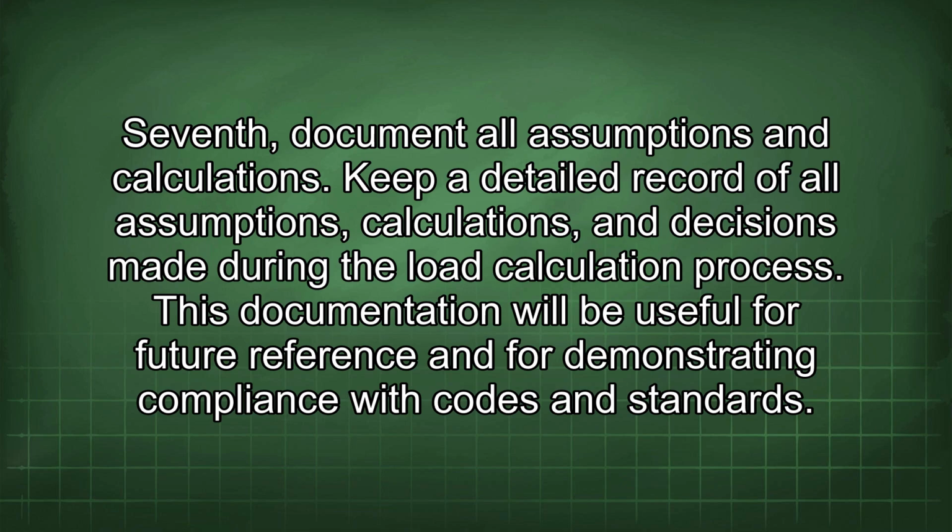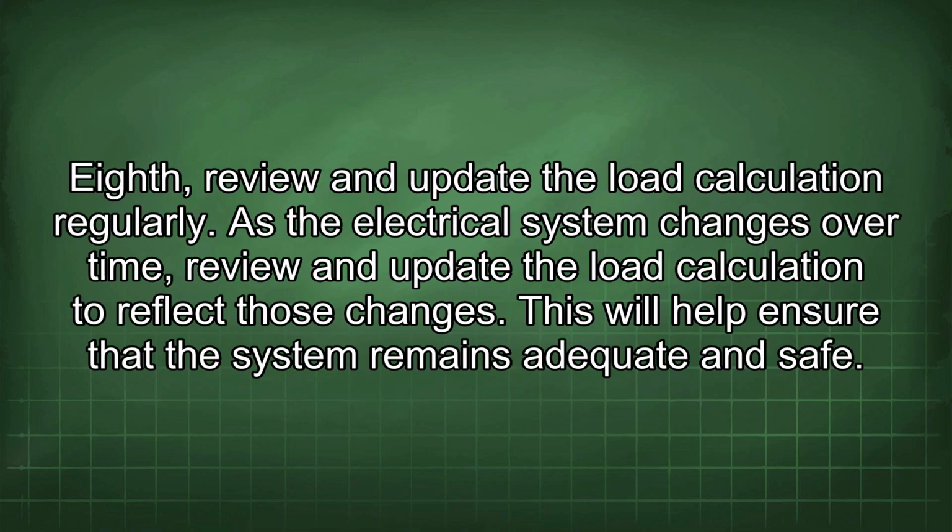Seventh, document all assumptions and calculations. Keep a detailed record of all assumptions, calculations, and decisions made during the load calculation process. This documentation will be useful for future reference and for demonstrating compliance with codes and standards. Eighth, review and update the load calculation regularly. As the electrical system changes over time, review and update the load calculation to reflect those changes. This will help ensure that the system remains adequate and safe.